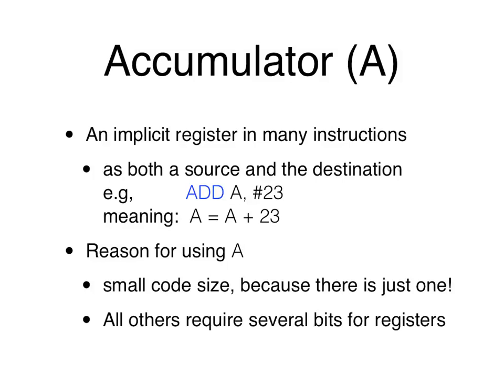Another architecture that achieves high density or code density is Java virtual machine or Java bytecode. Now Java bytecode does things a little different in that it doesn't have accumulator, but it uses stack concept. So everything is popped off stack and then pushed back on, push back, pop, and all that. But 8051, it has registers and accumulators, but it can really encode things very tightly.